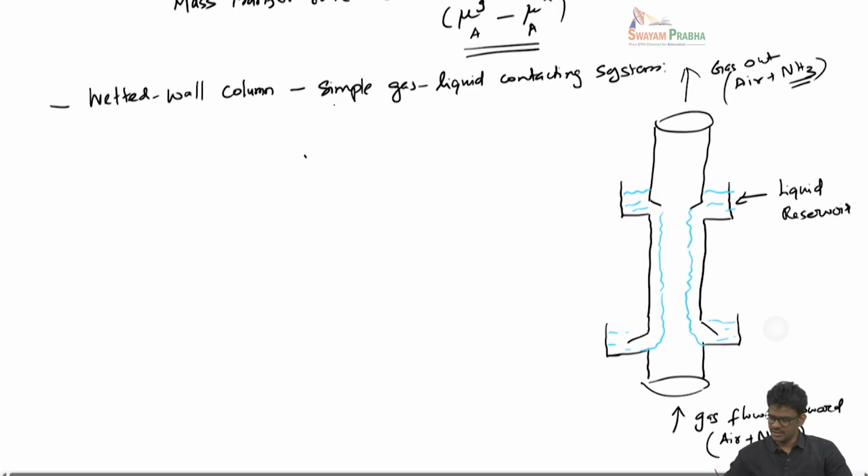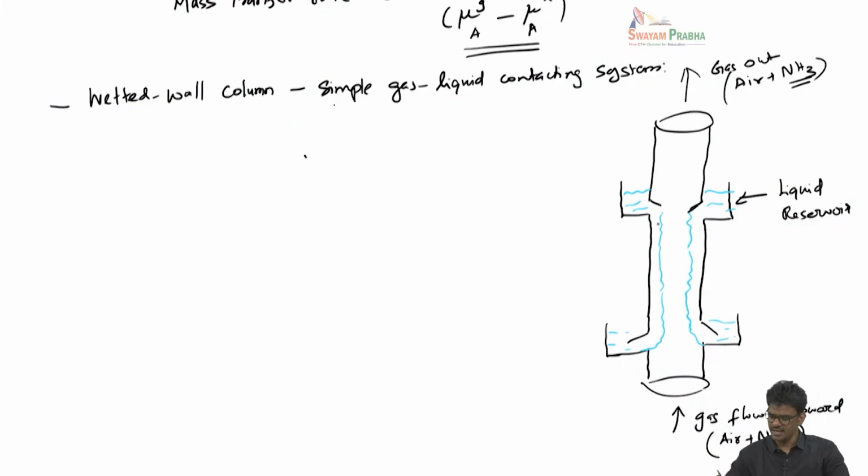And through this particular mechanism, the water basically flows into the pipe, not as a bulk, but as a thin film surrounding the inner walls of the tube. Okay, so it trickles along the inner wall of the pipe. So this liquid flows downward because of gravity. Okay, the thickness of this film here can be controlled by the opening here.